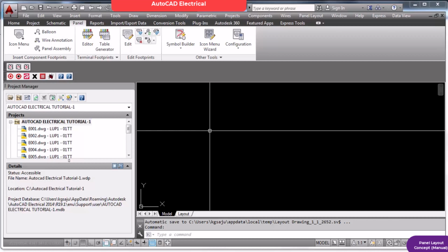But if I make this layout in 1:1 scale, I cannot accommodate this much height panel in an A4 size sheet, which is 297 by 210 mm. So there are two options. Either you make a layout first, then make it as a block and scale it without changing the dimension text. The whole drawing size you can reduce, but the problem is when you measure those drawings in the soft copy, you won't get the scale. So that is not the proper way.